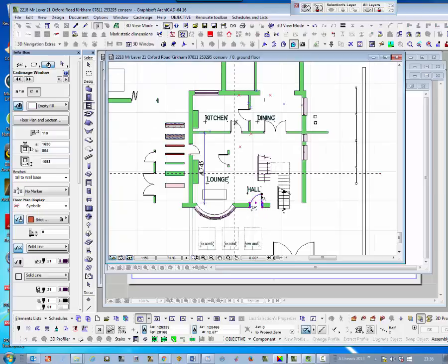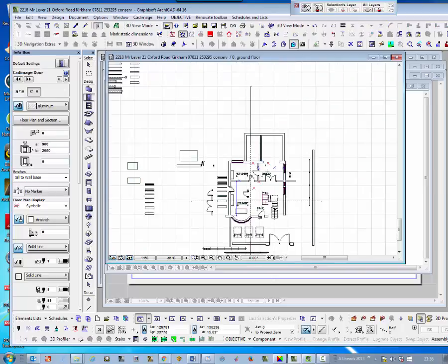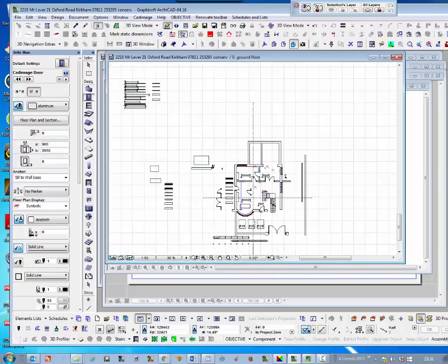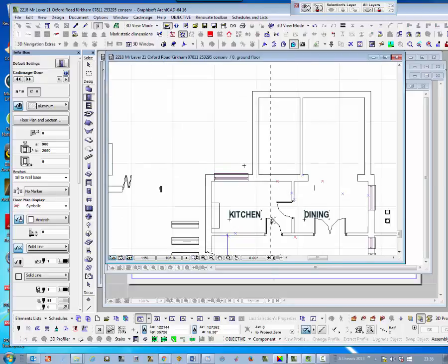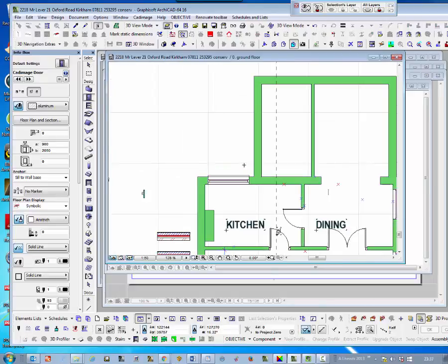Now then, I'm going to use this door down here. So I'm alt clicking on that door. To get to these parts of the drawing, I'm basically using my roller to roll it out and then roll back into where we want to be. There's a door in this position here, which is actually 880. So 880, as I say, we're going to add the frame onto these, so 980, and we can put that door in that position, and it's opening inwards in that direction, and it's not swinging that way, the hinges are on that side.